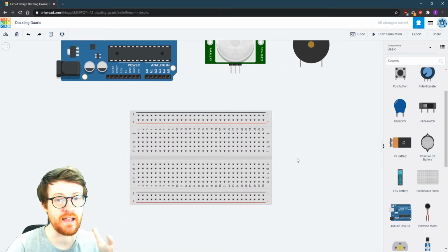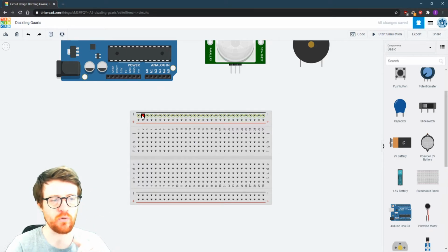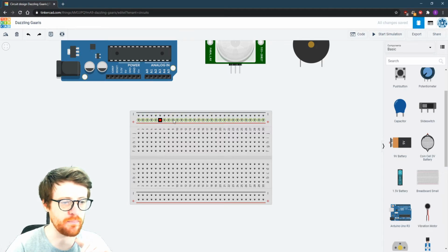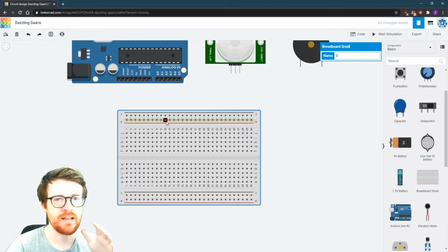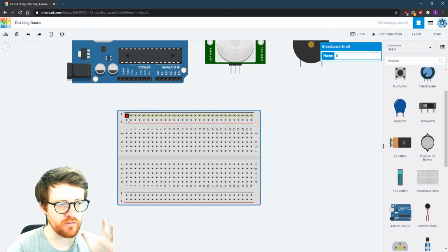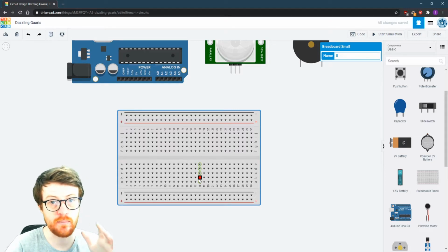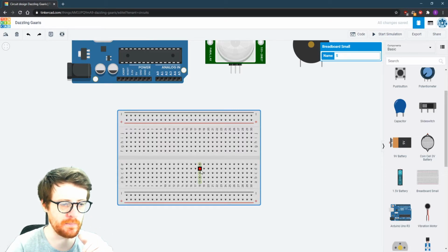A breadboard is a series of connected pins that can be used to plug in components. This black line is used for the negative. We have a positive rail, and then we also have smaller 5-pin sections on the top and the bottom. Anything that has a green circle on it means that they are all connected together. So this positive rail is connected all the way along, and these 5 pins are connected from the top to the bottom on line 18, and then there also has a separate one underneath as well.